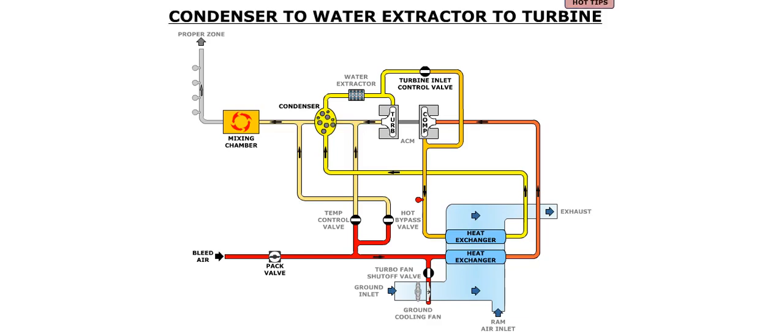The condenser uses the cool compressor air that flows through the secondary heat exchanger. This air flows through the condenser, and then flows through a water extractor which removes moisture from the air. From there, the air flows through an expansion turbine which rapidly cools the air.